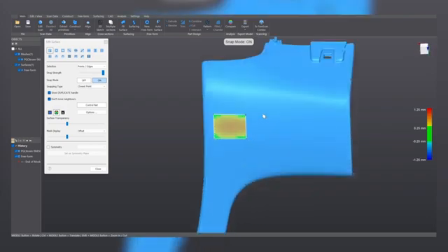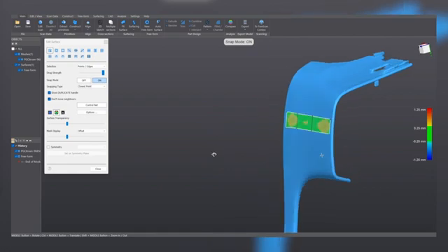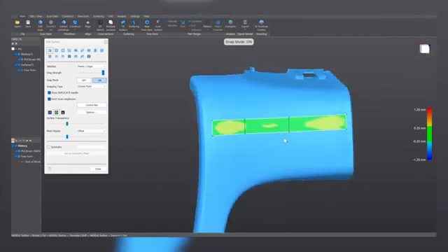And we are going to extend, let's adjust it a little bit. We are going to extend this face, creating new faces to cover the surface of this mesh. To extend an edge, you can double click on it. It turns yellow, and then with the D handle, you can extend the surface.